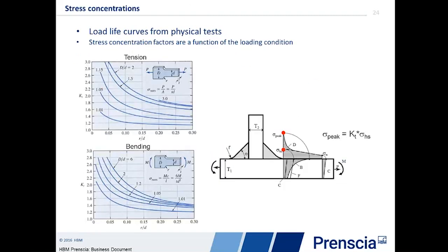Now, this has some issues. The curve that we've created is actually describing the weld, and it's using a stress value that's much, much lower than the actual stress at the toe of the weld. That means that baked into that SN curve that we're going to create is the stress concentration factor at the weld toe.